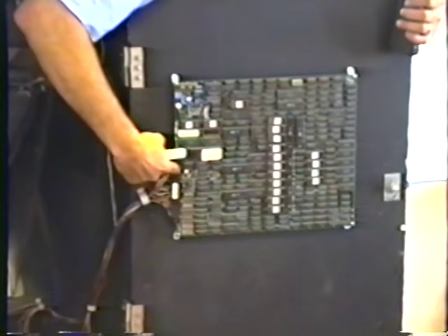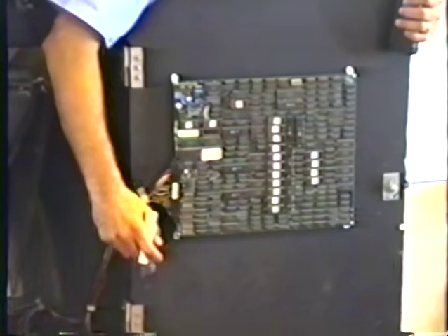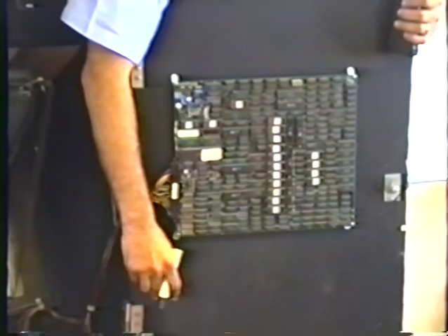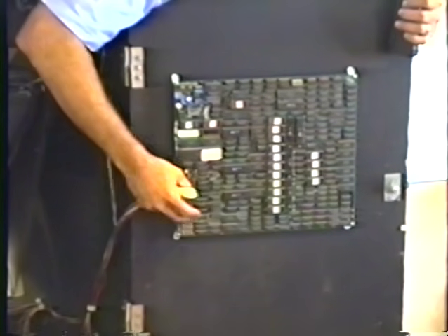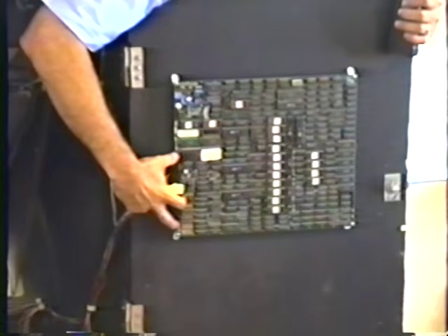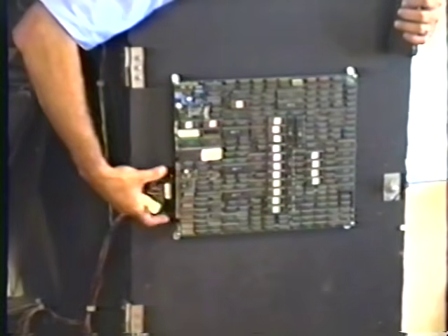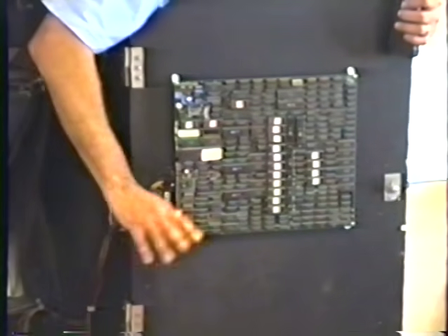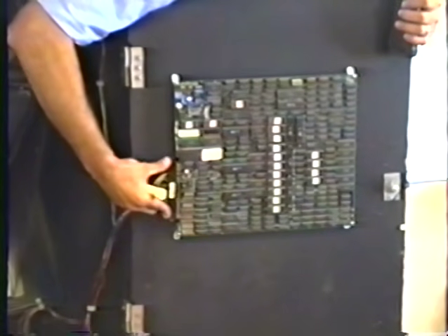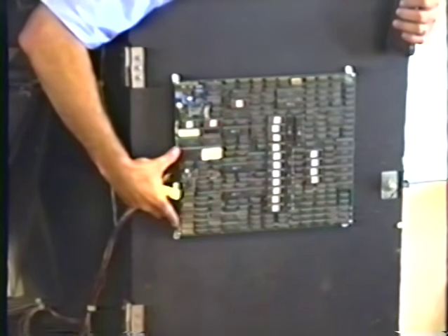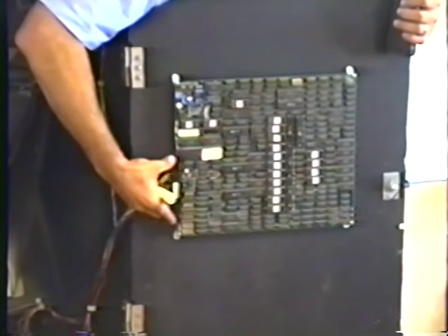If that's dirty at all, it's real easy to lose a tenth or two of a volt. You don't want to adjust the power supply until you've improved this. So before you adjust the power supply, I do this all the time. At the very least, with the power turned off, because you never plug in anything or unplug it with the power on, other than the AC power cord, obviously, you might try plugging and unplugging this a couple of times.